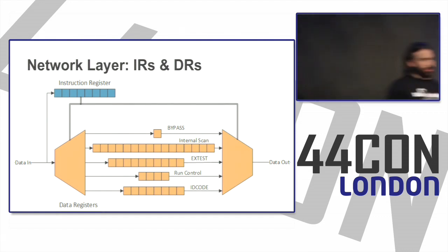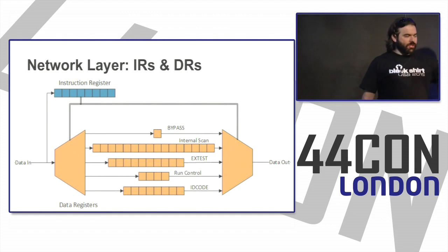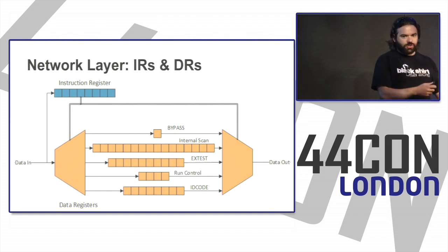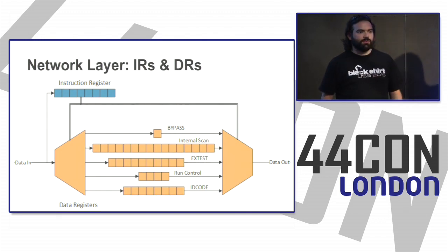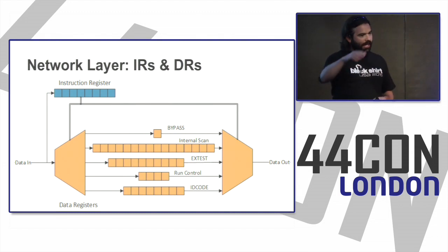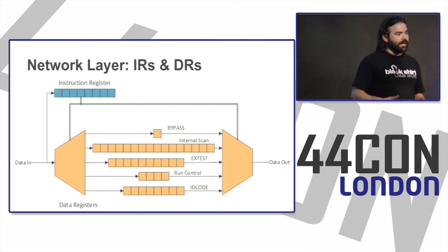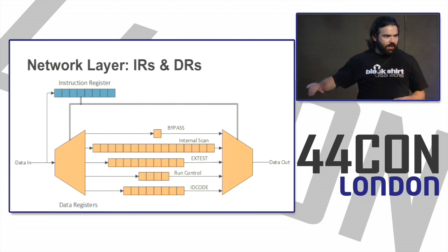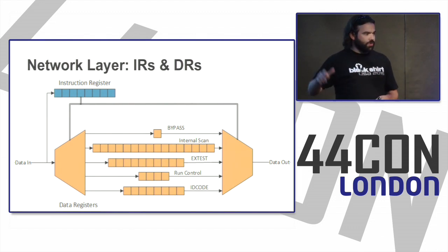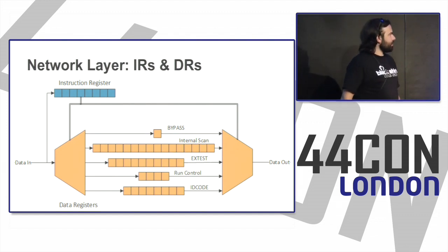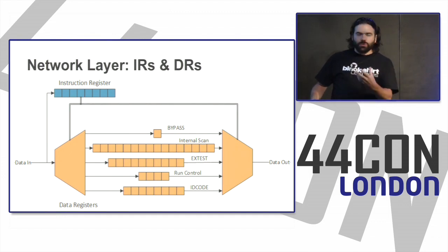When we use the word register, we're referring to a hardware register. So we're not talking about R0 through R15. We're not talking about AX, BX, CX, DX. Those are the instruction set registers. There's software registers and general purpose registers that you use to do stuff. From a hardware perspective, when we say register, we mean bits of storage scattered throughout the chip. They could be accessible from software. They could have a name like MSR or something like that. But it's also very likely that they're just a hardware value that's somewhere in the chip stored in a flip-flop, a little electrical circuit that stores a bit. Could be 1 bit, could be 10 bits, could be 372 bits. 1,000 something. Yeah. So that's what we mean when we say register.